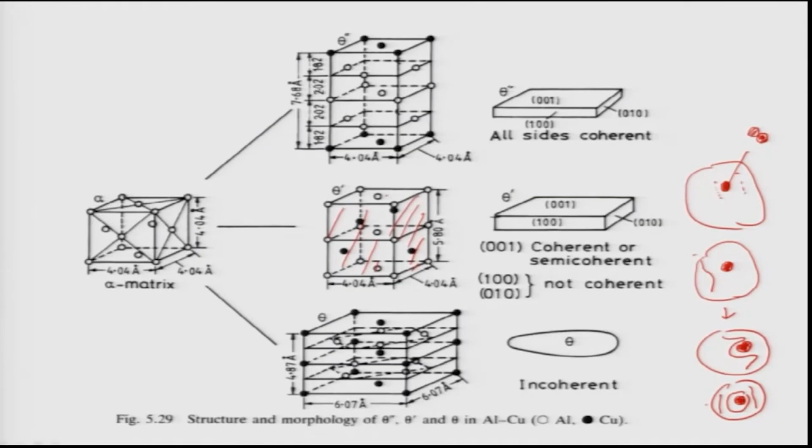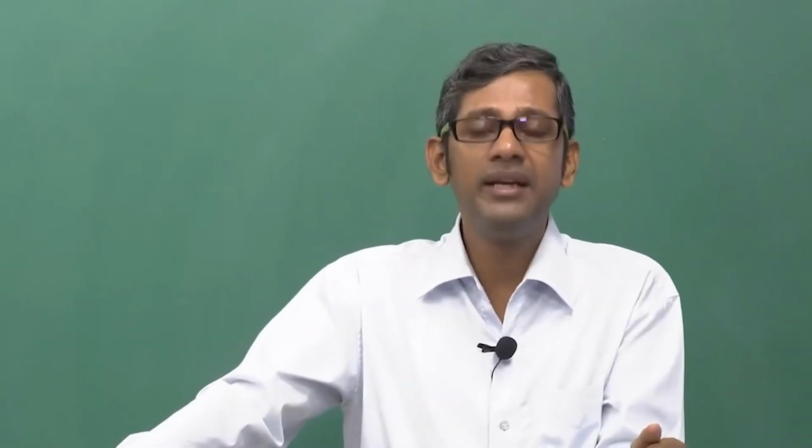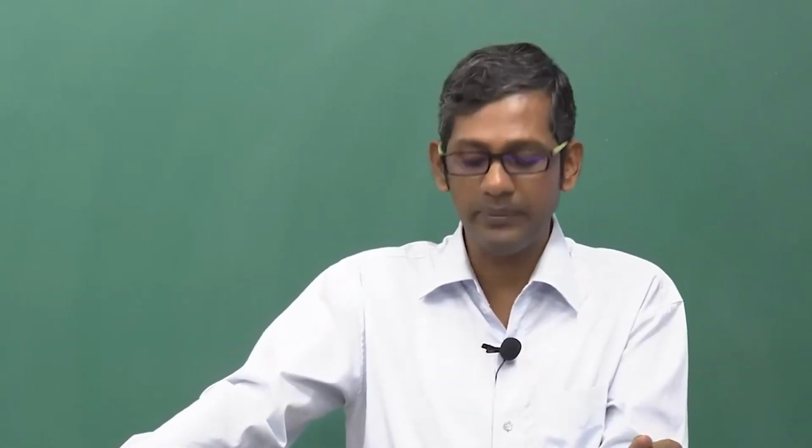So, with more dislocation passes, more loops will be forming around these precipitates, and the stress field generated will be higher, and that gives this strength. But remember, this depends on the distance between these precipitates. The precipitates have to be at a particular separation, otherwise this kind of bowing of dislocation leading to formation of a loop will not happen. That is why the precipitate size must be a little bigger as compared to theta double prime.